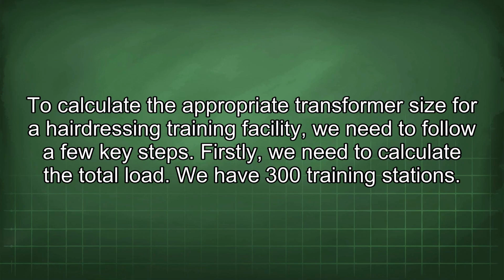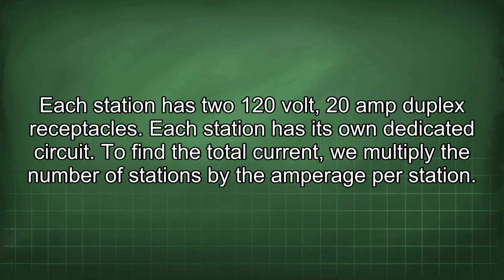To calculate the appropriate transformer size for a hairdressing training facility, we need to follow a few key steps. Firstly, we need to calculate the total load. We have 300 training stations. Each station has two 120-volt, 20-amp duplex receptacles. Each station has its own dedicated circuit.